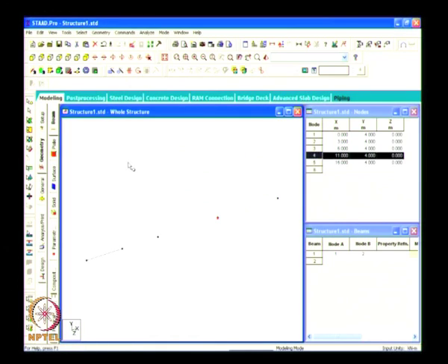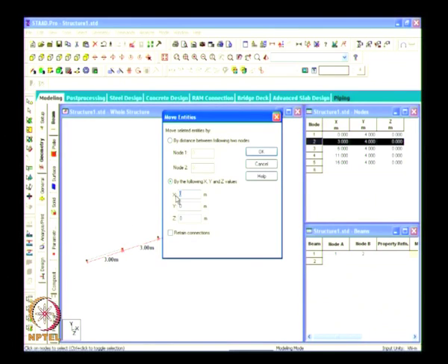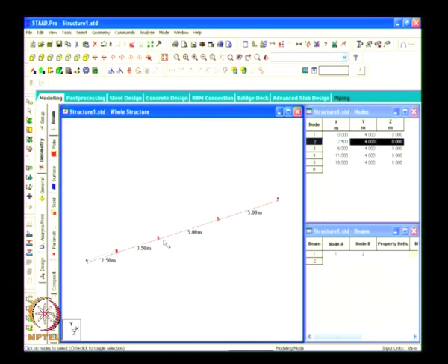Two meter you have to create, no? Where is it? Just roughly calculate. Correct. 2.5 second one. So this is the top deck which is modeled. He has given some random number. Now we will put exactly how much we need. The distance between the C side to this first row pile is 2.5. So he has now made it 2.5.